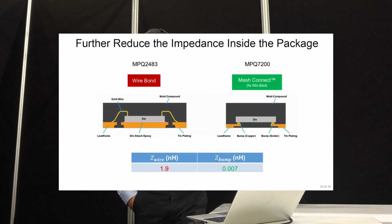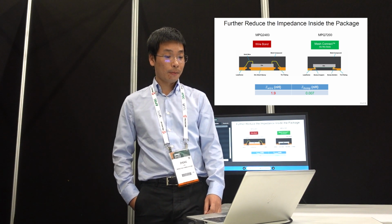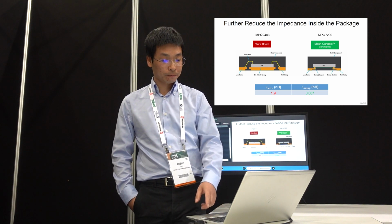Another thing: we reduced the impedance from the board, and then is there anything more that we can do? So here is another step. We basically still have some wire bond impedance inside the package, so what we do is remove the wire bond, and using the copper connection, we call it mesh connect, to directly solder the die on the lead frame, so we can get rid of this 1.9 nanohenry.